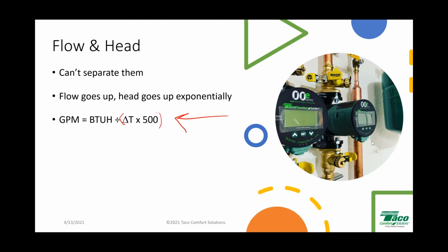There are some exceptions to that rule. Residential radiant floor heating is often designed around a delta T of 10. So the water might go out at 120 and come back at 110 for an average of 115. That's done for the consistency of floor surface temperature, so you have warmer spots and then less warm spots, so to speak. Indirect water heaters might be designed around a delta T of 30, meaning maybe the water's going out there at 190 and coming back at 160 perhaps. And then with ModCon boilers, you can pick your delta T across that heat exchanger, which is basically a different webinar. But that's the delta T.